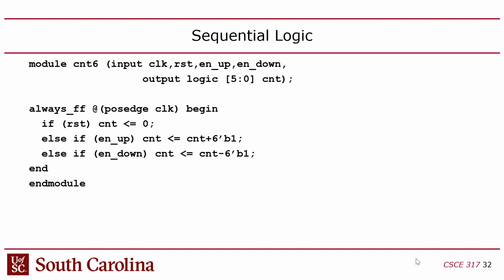See, this is, by the way, symptomatic of the problem I mentioned earlier, which is, why have one always that can do combinational logic or sequential logic? Why do you have this one statement that can do everything, and then you've got another one, the assign statement, that can only do combinational? That's dumb. Yeah, it is, and it creates problems because it's a way for bugs to be introduced. Well, in SystemVerilog, they introduced this underscore FF and underscore comb, which is an attempt to fix that problem, which is a way to tell the compiler, hey, I'm trying to create clocked logic here, so if I didn't do it right, then flag it as an error. If you don't put the FF, you don't have to, but then the compiler doesn't have a way to check you.